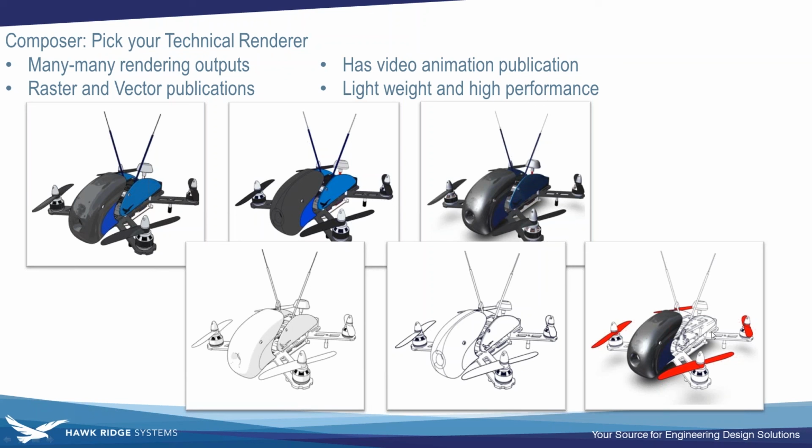Basically how that works. So instead of saying, hey, globally for all the models here, we're going to have this shaded technical drawing, you could say, hey, this part is shaded, this part is silhouette, this part is technical styled, and then you can create these really cool outputs to really define areas of the model. It's really great for assembly instructions, so you can say, hey, the red parts are moving right now, we're assembling them, now we're going to assemble the green parts, and so on.